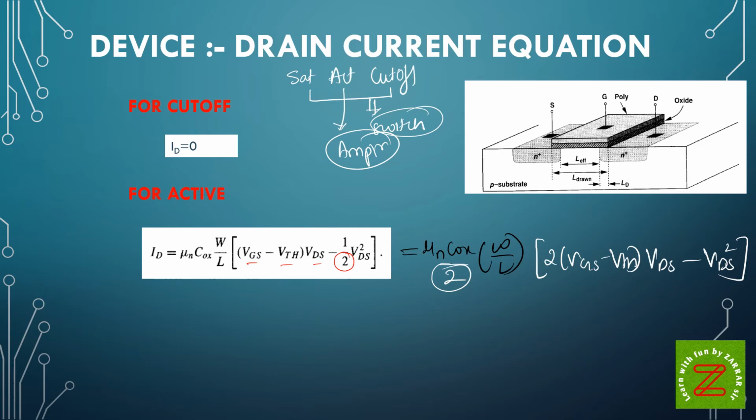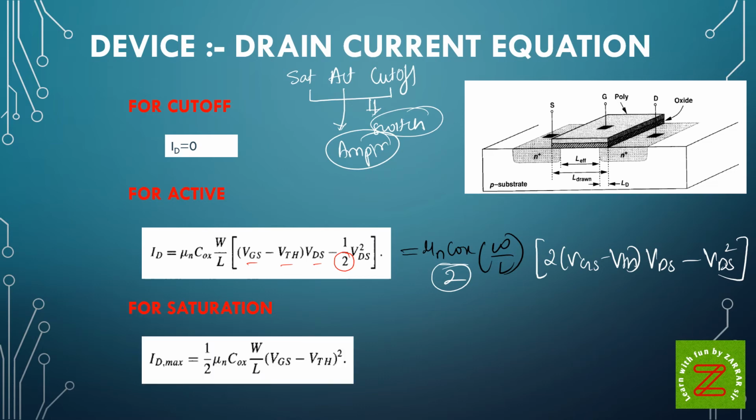The reason why I have done this is, you will be surprised to know that for saturation the equation is, see, you can see this term is common, mu n Cox W by L upon 2. So this term is common over here, and you only get (VGS minus VTH) the whole square. So this is the equation for saturation.